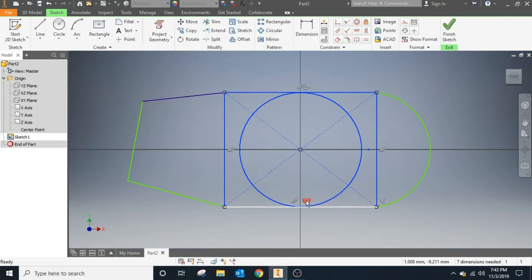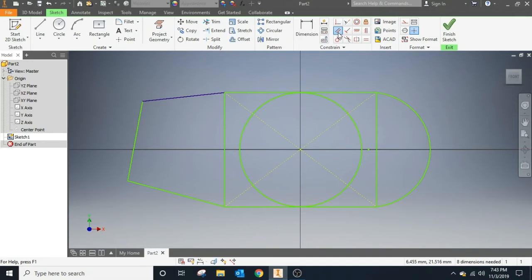So you got a lot of different constraints. This is constraint to be horizontal, which is another one you can see up here. It's the horizontal constraint. These are perpendicular to each other. I think once we delete this horizontal, we should be good to go then. And I can make these perpendicular, and the thing, yeah, there you go. It'll rotate. So that's how you saw a couple different constraints, how they work.